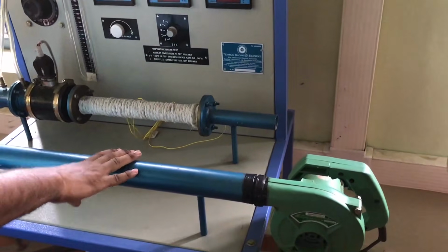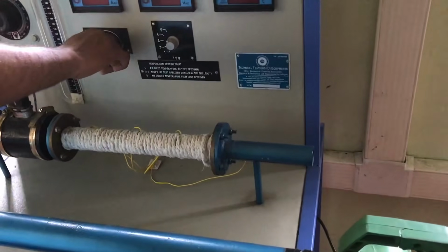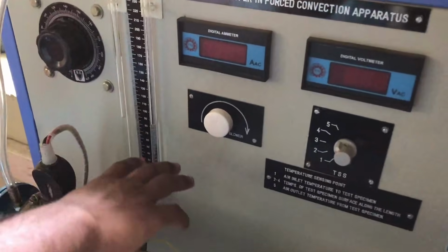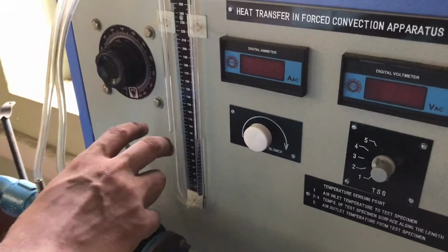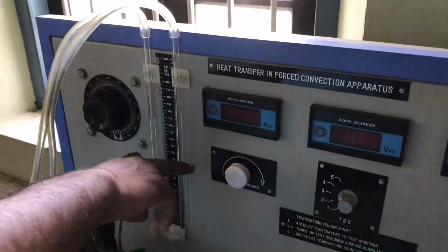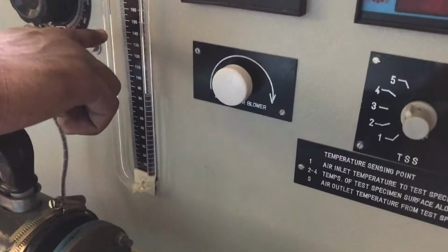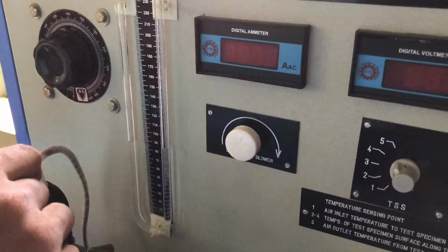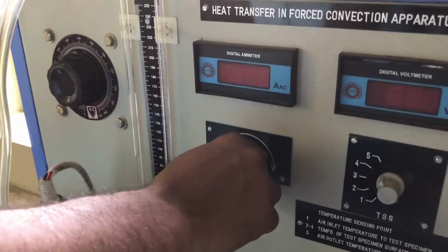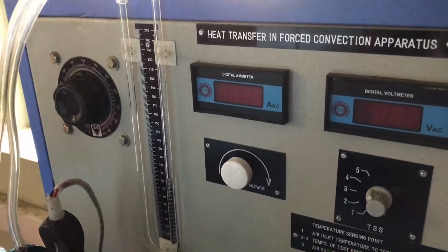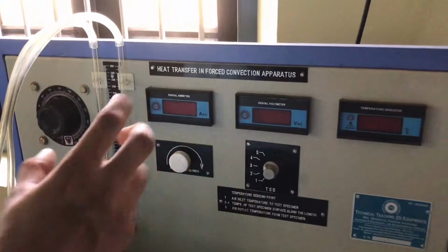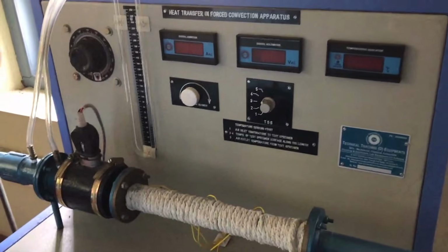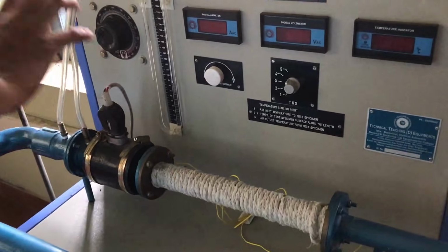As we increase this flow, there will be a level difference in this U-tube manometer, and because of that we are able to note the level difference. Let us say that here the reading is H1 and here the reading is H2. We should set this dimmer at a position so that we are able to control the flow at a given level difference. It will be given in the question that the flow will be at this much height level difference, so we should keep that.